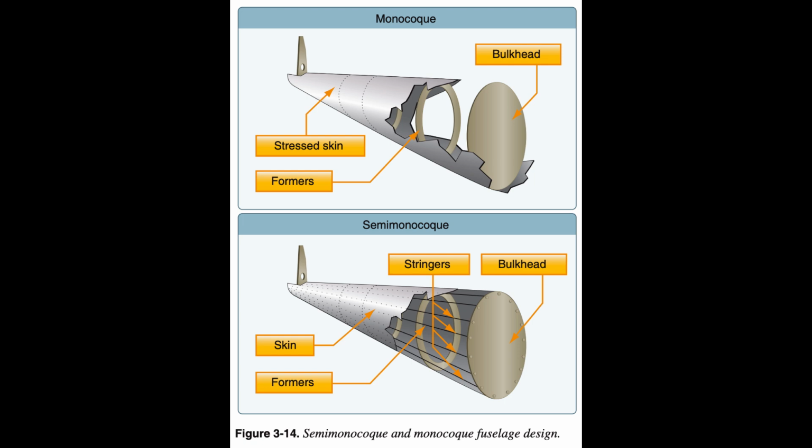To construct the half-shells, rather than gluing many strips of plywood over a form, 3 large sets of spruce strips were soaked with glue and laid in a semicircular concrete mold that looked like a bathtub. Then, under a tightly clamped lid, a rubber balloon was inflated in the cavity to press the plywood against the mold. 24 hours later, the smooth half-shell was ready to be joined to another to create the fuselage. The two halves were each less than a 1/4 inch thick.